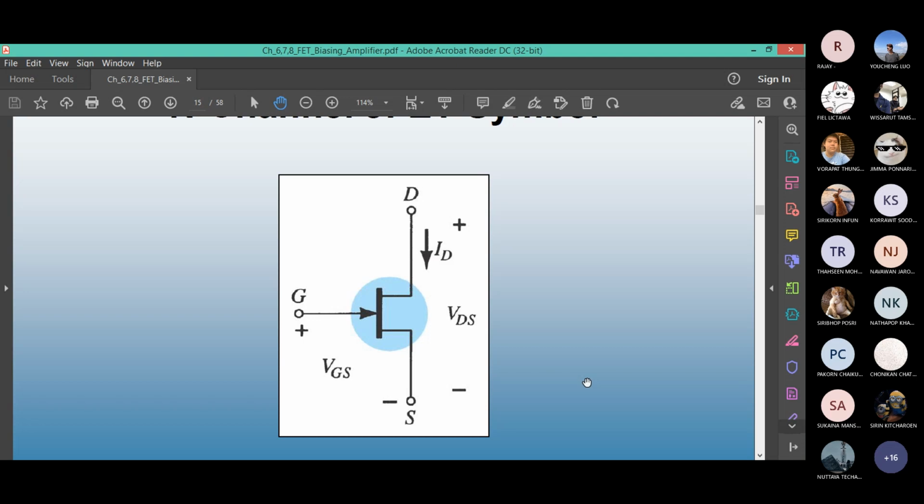What's... The current will go down. What if you have such a high input impedance? First of all, what's the unit of impedance? Ohms. So you are using the same unit as resistance. So if you have a very high input impedance, what does it look like? What type of circuit? Open circuit. A very high resistance. You cannot have an infinity resistor in reality, but maybe mega ohm, 10 mega ohm, that's very high, that almost no current will flow.